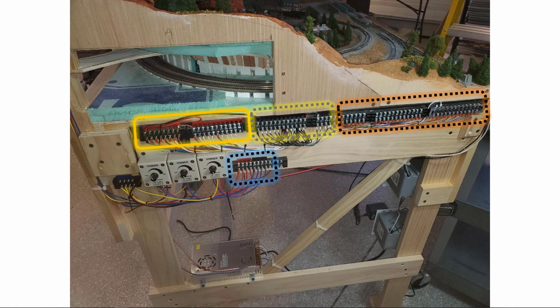So the first one on the upper left, now you can see that I've got, for the most part, all but one of the isolated zones rewired, re-terminated, but they're still jumpered together. Okay? And then directly to the right, I've got the black jumper, and there wasn't enough on one terminal, so I've got a few more on the other terminal strip, and that jumpers all the other side together.